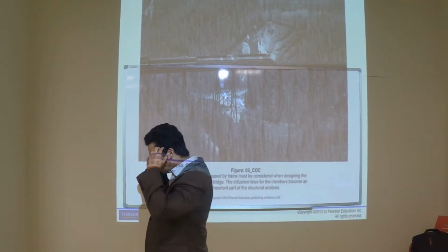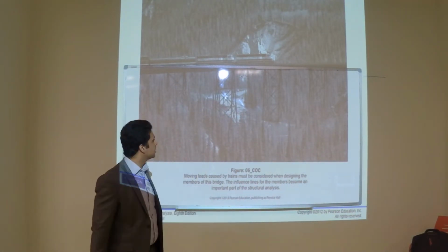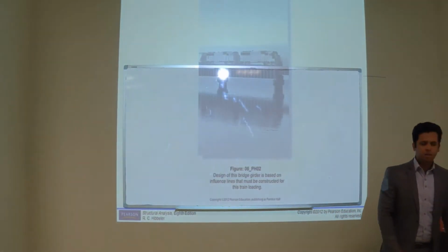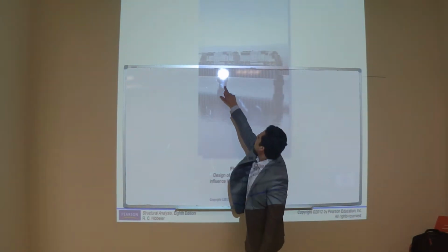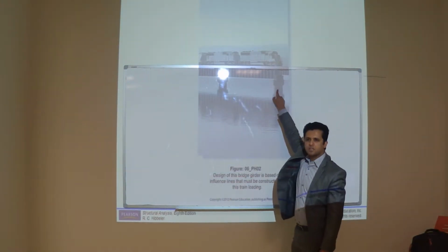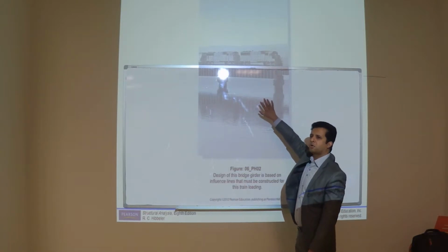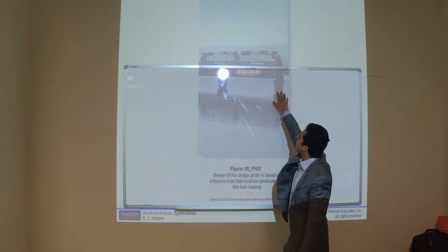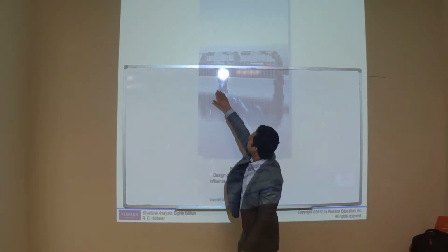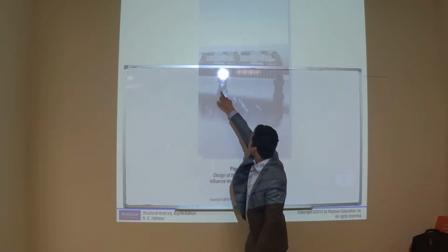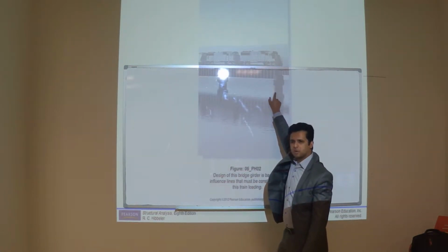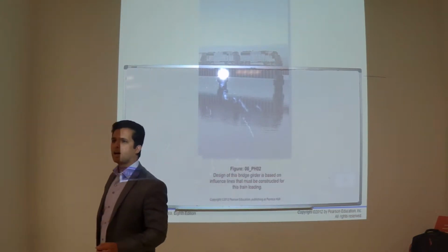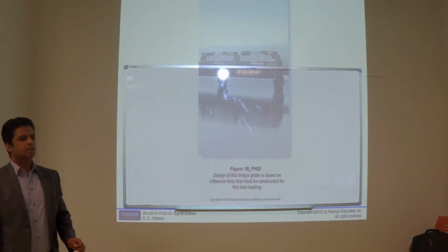Okay, first tell me one thing. You have two supports. For example, there are two supports, one support here, another support here for a bridge, and it is a simply supported bridge. I mean, the beam or the girder is resting simply supported. What do you think? When the train is moving, are the reactions here and here the same? No. At every instant of time or distance, the reactions are changing.